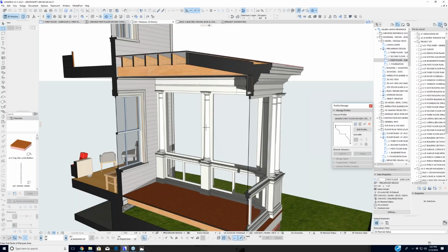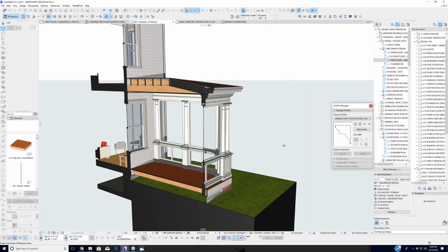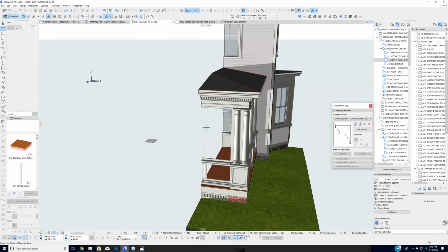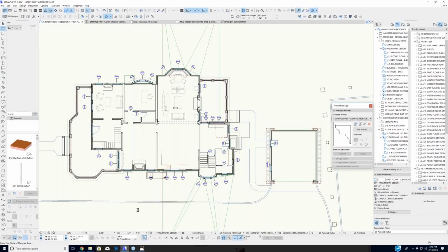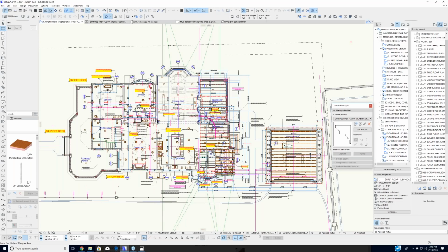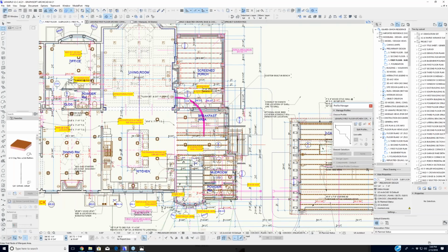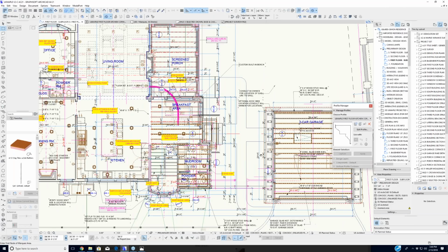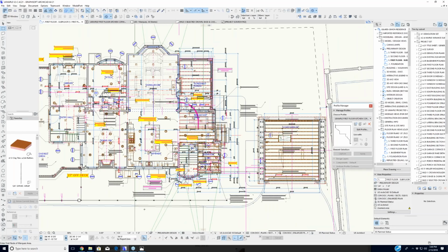All right, then let me just explain briefly, for training purposes. When you do a publish command in BIMX, in the publisher, you need to have a 3D view, or possibly more than one 3D view, in that publisher set, along with as many drawings and layouts as you want to include. Because BIMX doesn't have layer control in quite the same way, it doesn't have layer combinations, it will export one or two or as many 3D models as you decide. It can balloon up the file size, but you can have a structural and a full architectural, two different versions. You could have existing and new, two different versions. You could have several variations. And then in the BIMX file, you can just choose which one you want to be looking at. So that's in the publisher settings for the BIMX.